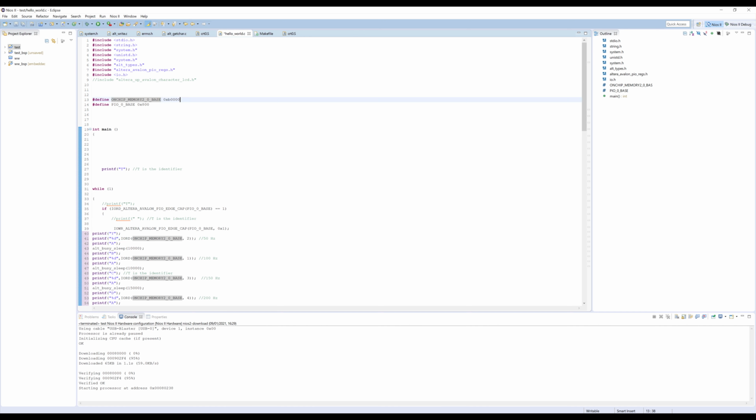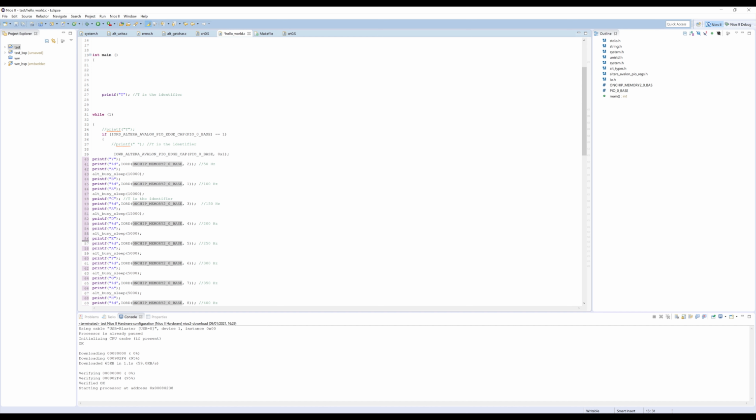Notice how that matches what we have in the Verilog code, 0xB0000. And you can see, if you go back a minute or so, that's the base address that we target. And then we use this IO read command, and that looks at the base address and the offset, and then it will printf that number over the UART into our graphical user interface.